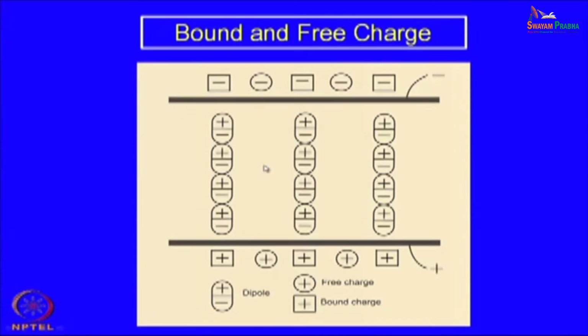Initially, we will find later on that these charges might not be forming dipoles or they are not bound to each other. So, they are more randomly distributed. Of course, in a crystal there is a certain amount of periodicity, but they might not be aligned. So, this alignment and formation of the dipoles is actually the phenomenon called polarization. When you apply an electric field to an insulator, the charges get polarized, and that polarization is what we call the dielectric polarization.